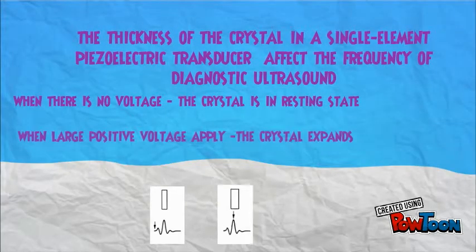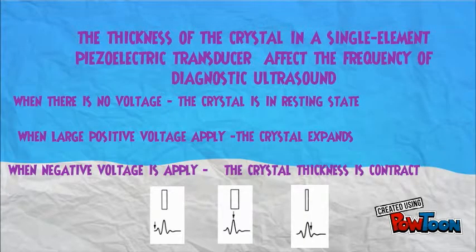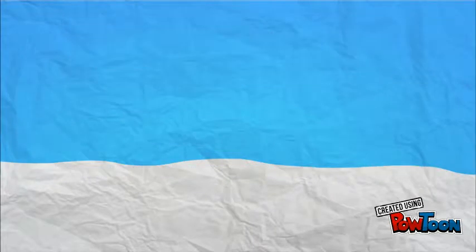The thickness of the crystal affects the frequency of diagnostic ultrasound. Let me explain in a simple way. When there is no voltage applied across the piezoelectric crystal, the thickness of the crystal is in resting state. When a large positive voltage is applied, the crystal is expanded, and when a negative voltage is applied, the thickness is contracted.